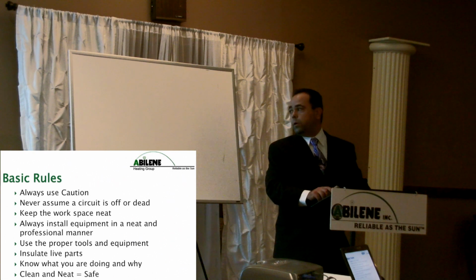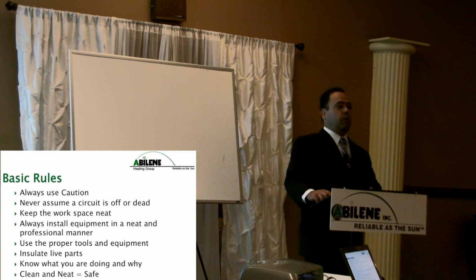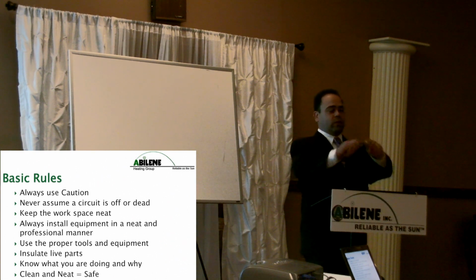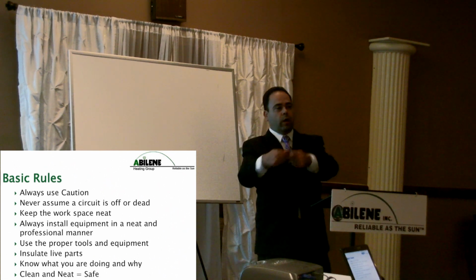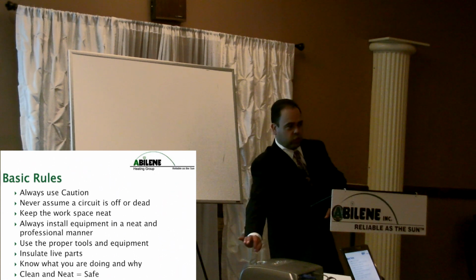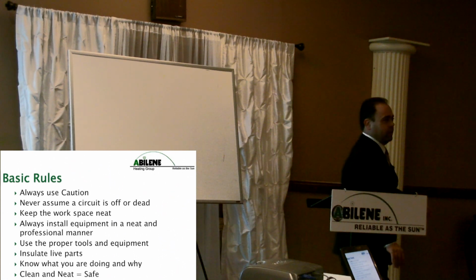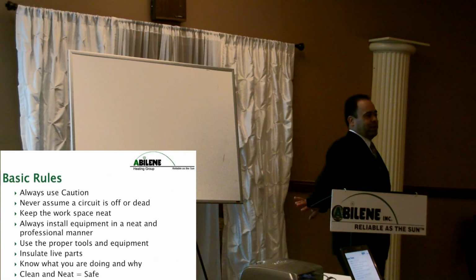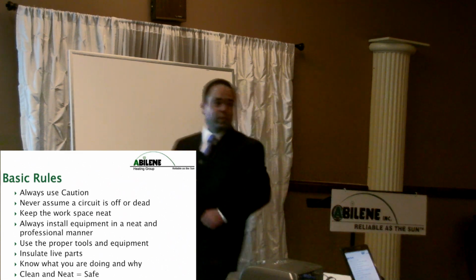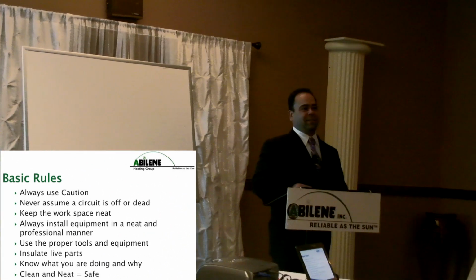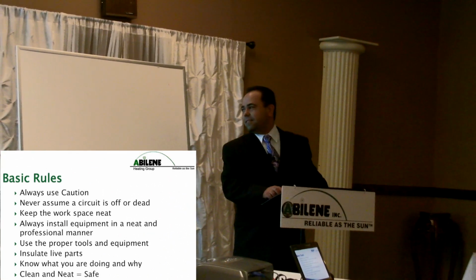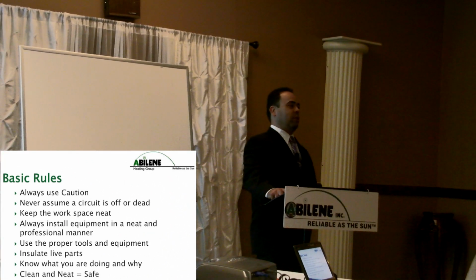All right? Very important. Always insulate live parts. Sometimes guys will know that a wire is open or alive. They'll open the wire, leave it hang, but make sure that it doesn't swing, and they'll walk away from it in a minute and not leave it insulated. And then some guy's going to walk through with a piece of pipe, bam, because he's going to hit that live wire. We've all done it. It's not right. You have to insulate the live parts all the time.